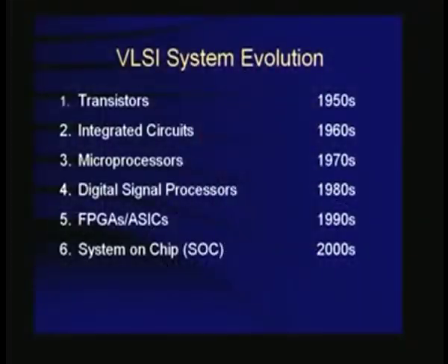On the other hand, we have another complementary part called FPGAs, field programmable gate arrays. FPGAs are similar to DSPs in the sense they are programmable, but they are not DSPs. The analogy stops there, at programmability, but these are specific functional. A DSP is an evolution of a microprocessor for signal processing applications. A microprocessor is used more for data processing applications like databases, huge commercial computers, whereas a digital signal processor was used for signal processing, which is most important in filters, FFT and things like that.